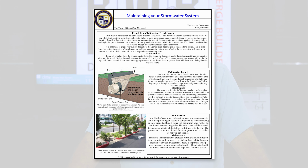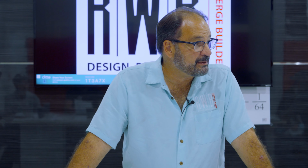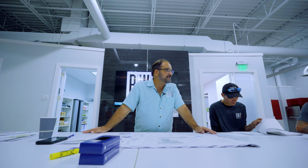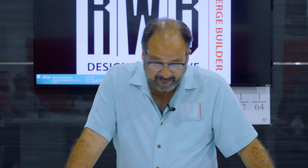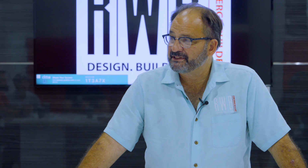It has a perforated pipe that runs through and usually gravel. The drawing will say how big it is, how tall it is, how wide it is, how long it is, and what the rock inside is, whether it's number 2, number 5, drainage rock, whatever it is. These are all specified and designed by the civil engineer for the specific application of this drawing.